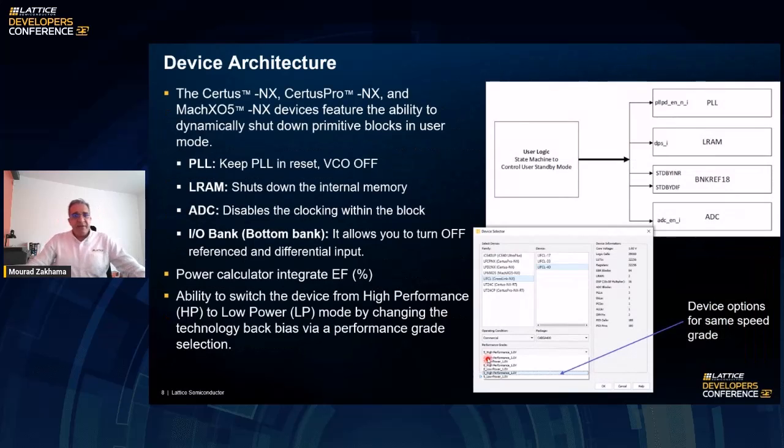Other device architecture elements: all the families that we see here, Certus-NX, Certus-Pro, and MachXO, all the Nexus family of devices, also have features that allow you to keep certain portions of the device in shutdown mode or in low power mode. For PLLs, we have a keep-PLL-in-reset option, so the VCCU is off. There's a pin that you toggle to put the PLL in a standby mode, so it minimizes power consumption.